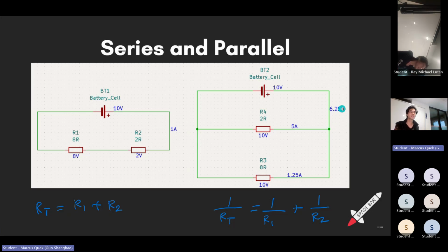Okay. You can think of it as like you have two thin pipes, which are the resistors, right? And you put them next to each other, the cross sections of them add up, so more current can flow through. Versus if you put the thin pipes in front of each other in series, now you have to go through both resistances, so it's harder to push current through. This is the water analogy of series versus parallel. All right. If that helps, then good.